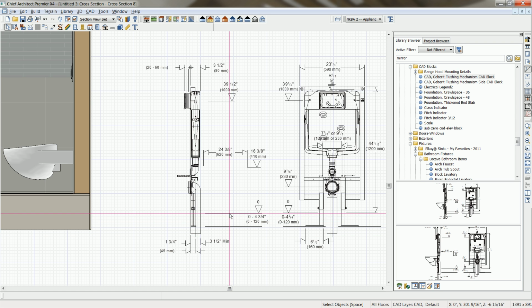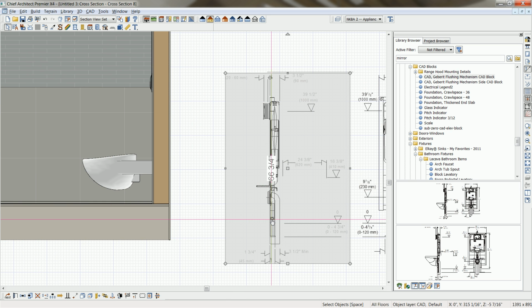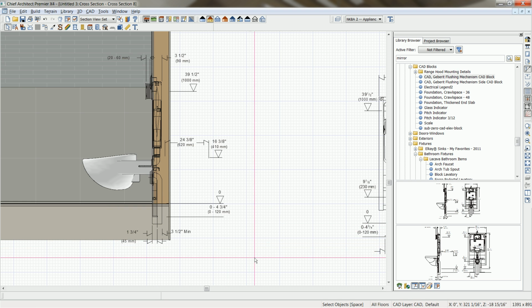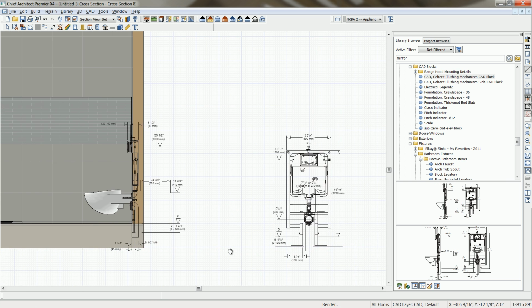cavity. And in the detail here, this is the point of floor 0. And I'm going to assume for the purpose of this demo, that's my finished floor. So if I come over here, I'm going to highlight the detail. I'm going to use a point-to-point move. And I'm not going to worry about being overly precise for this. I'm going to come in where that meets the intersection and we'll snap that into place. So now I've got the detail of that section.